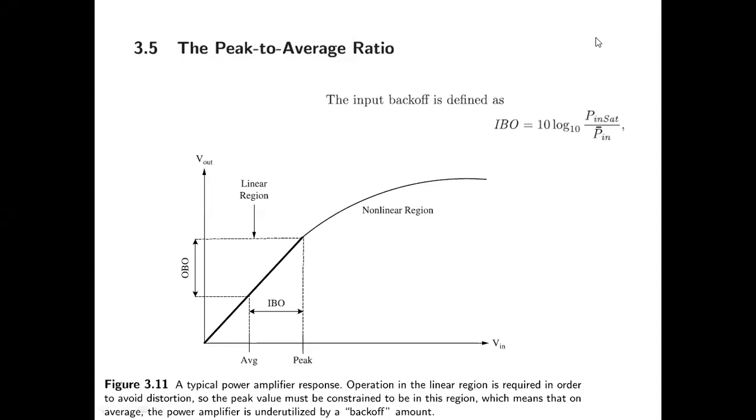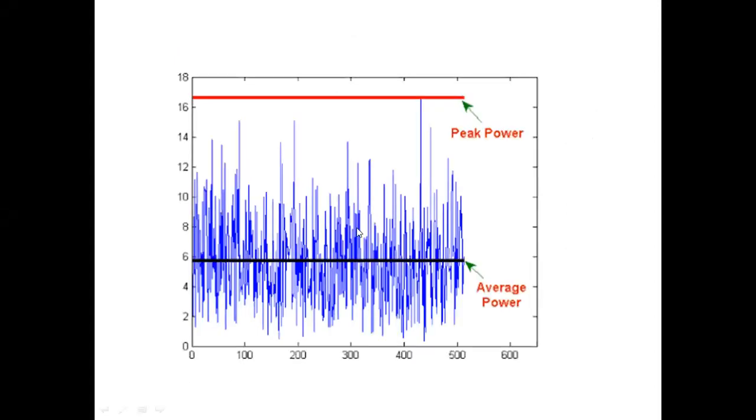So, hello everyone. In the previous video, we spoke about how the peak to average power ratio can be a battery vampire, right? So, it's all about if your signal has a pattern something like this, where there are occasional peak values that are much higher than the average power, then your power amplifier needs to be unnecessarily biased, consuming higher voltages and higher currents, and thereby leading to inefficiency and battery consumption.